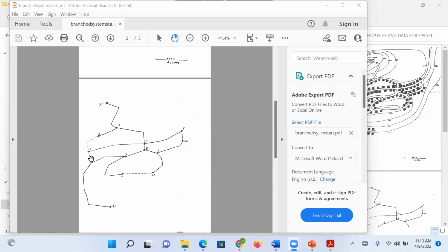But node 6 already has an offshoot, somebody downstream, and for water to get to that person, water must flow through node 6. So it means node 6 is accommodating its own demand and the demand of the person going downstream. Therefore, node 6 will now be 0.28 plus 0.87. That will be the value for node 6.